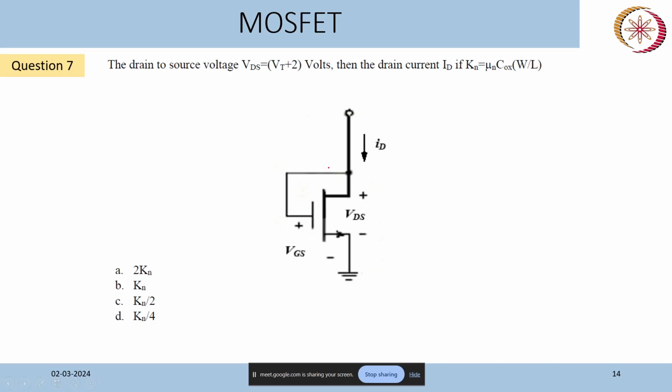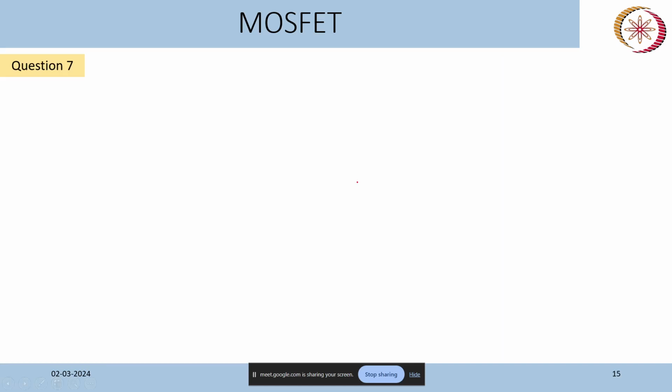So this MOSFET is operating in the saturation region whenever you see the gate and drain terminals connected.